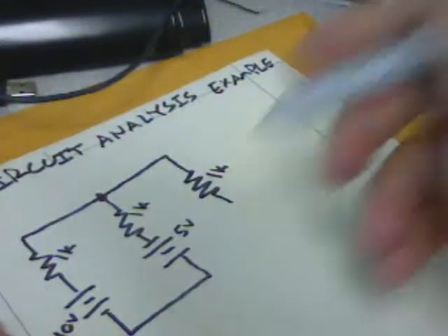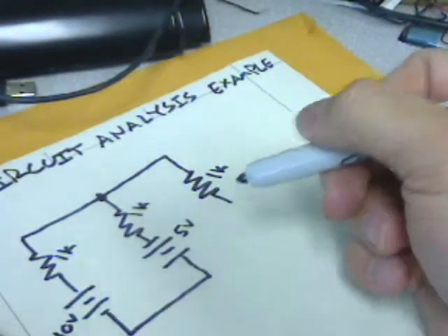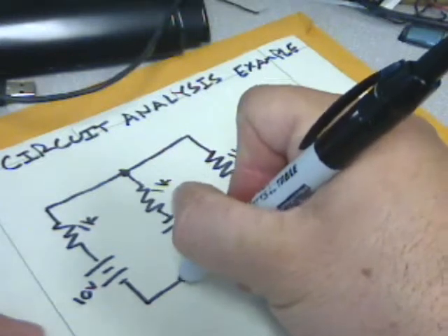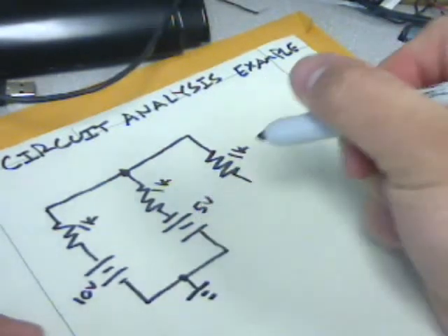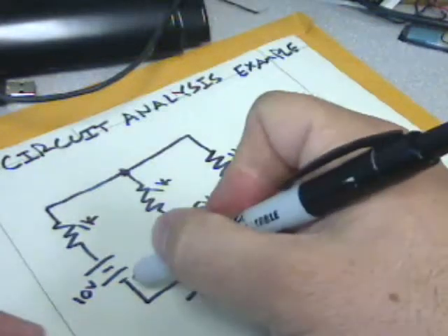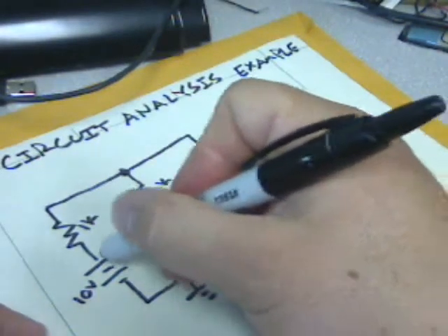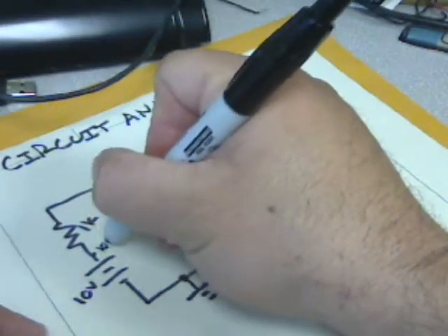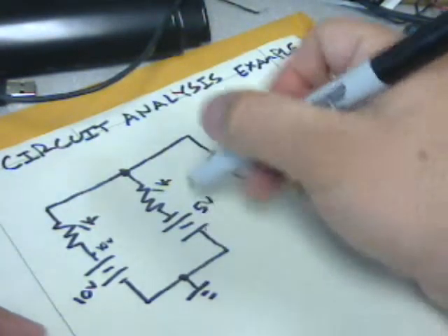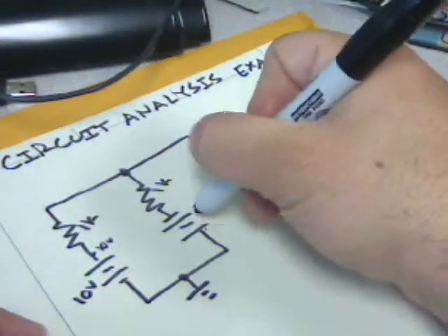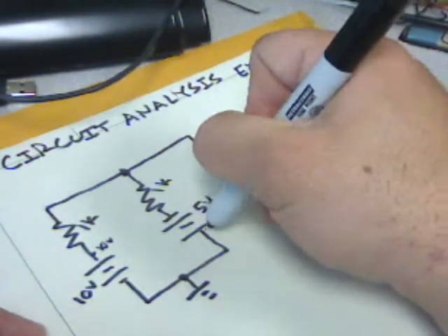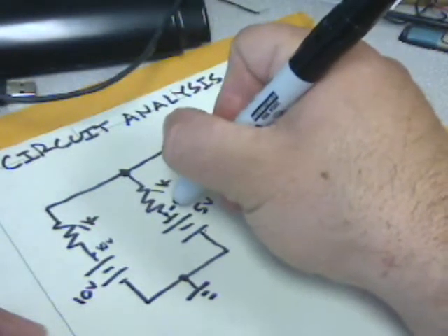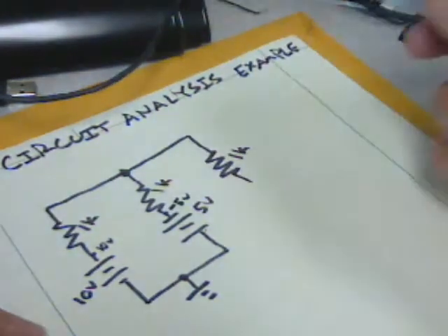Now, one thing in our circuit is we want to set up the reference voltage, meaning the 0 volts. We want to determine where that 0 volts is, and so I want to say 0 volts is right here. There's a 10 volt difference there, so right here we know we're going to have 10 volts, and because we have 0 volts here, this is an upside down power supply, which means that you're going from positive to negative. It means that this is 5 volts more negative. That means we have negative 5 volts at that point right there.